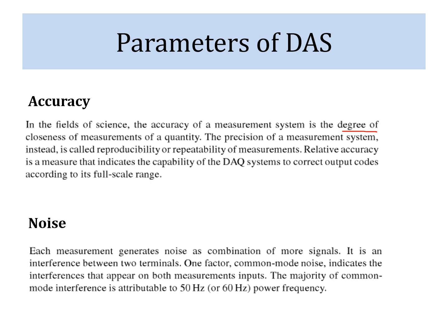Then we have noise, and it is again similar, like where there is interference, where there is a common mode noise, they all come under noise, that is, an unwanted signal is known as noise. And usually in this case in data acquisition system, because we have power signal also, most of the time we are handling 50 hertz power frequency as a noise. Although we have many filters in data acquisition system hardware, but still we have to take care about how much noise carrying capacity is there within the system.